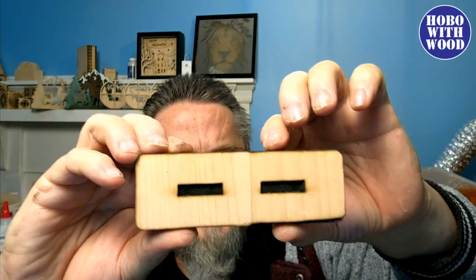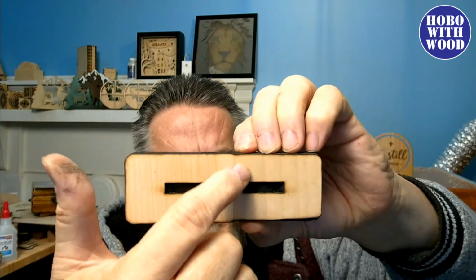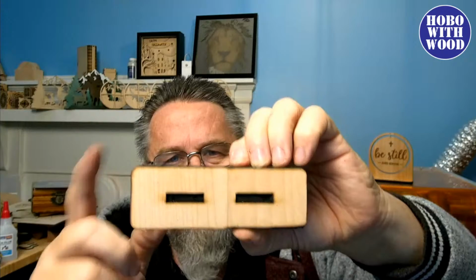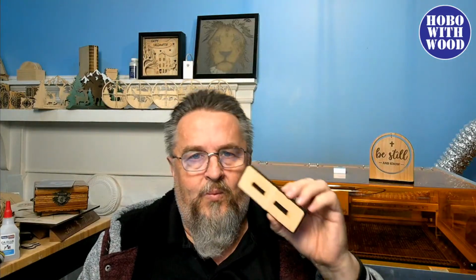And the difference is, you see that seam that runs right down the middle? It's all maple, but it's two pieces of maple that have been glued together. One piece of that maple is so much more dense that the laser would not cut through it. I had to go over it and over it and over it. Finally, I switched from the 10 watt to the 30 watt to try and cut through it even more, and even that wouldn't get through it.